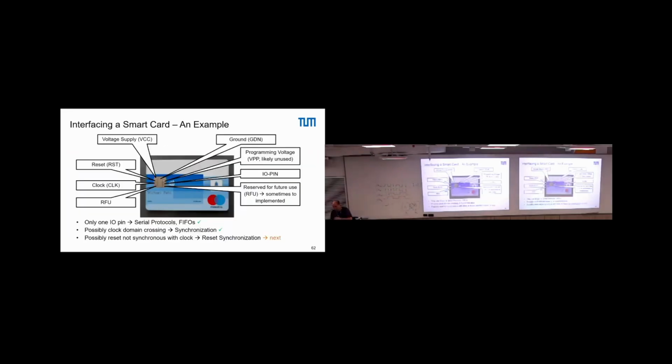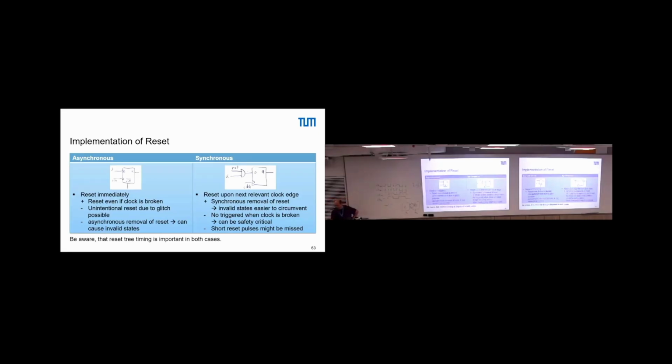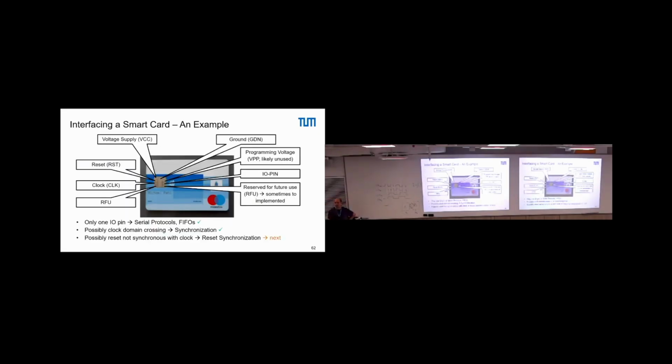Then what is still open is the synchronization first. Synchronizer, the reset, that we did not talk about yesterday. For the reset, we have two cases, classic cases again. We can have a synchronous or an asynchronous reset. To give you quickly